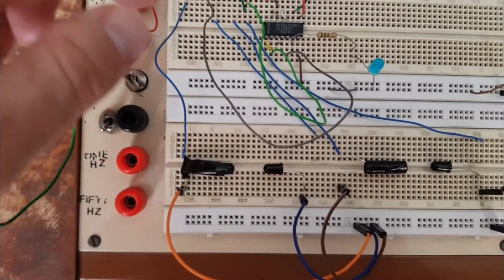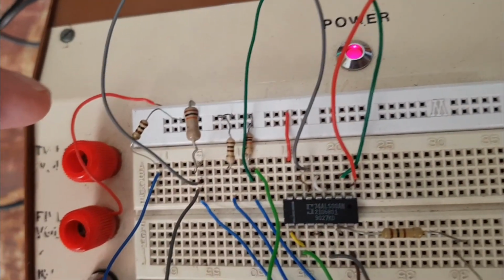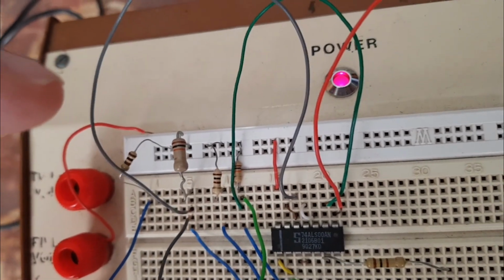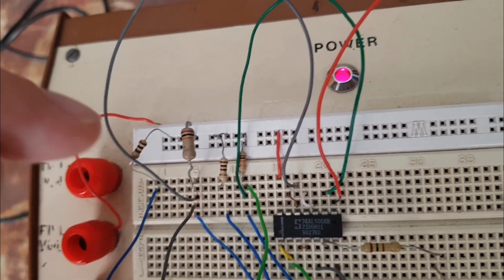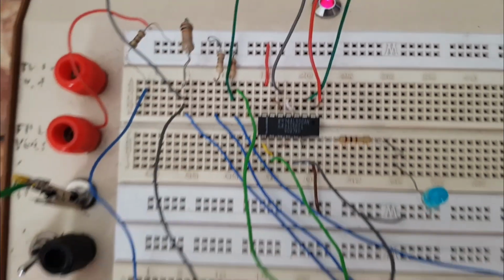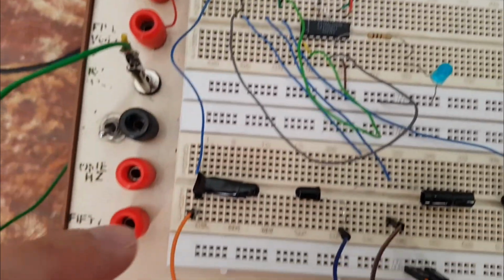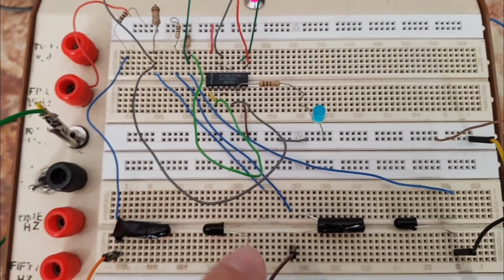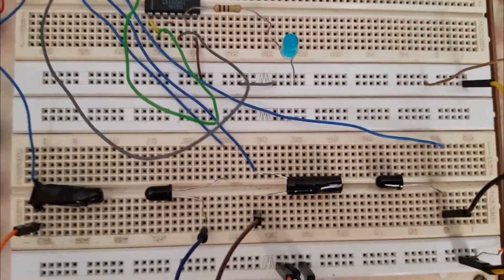The only difference is now I've got all of my resistors here wired to the top, so you'll see that there's the 100 ohm for the first IR LED, then the 10K, then 100 ohm, then 10K. You can also see that I've made blue wires to go to the first LED, then the second sensor, and then the next LED, and then the next sensor.